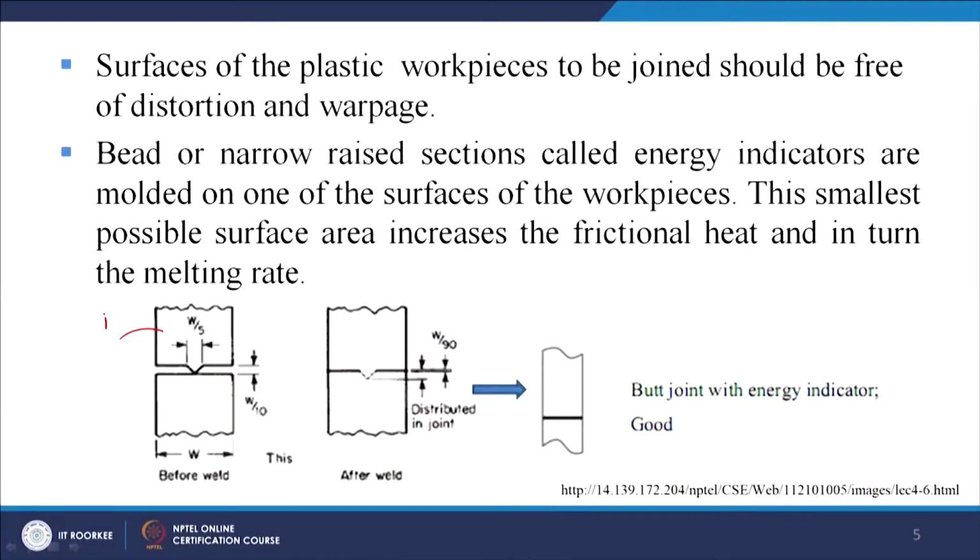One by one we will try to see, and with the help of the diagrams we will try to understand how we must design our joints so that they can be in mechanical motion under the frequency just mentioned, so that frictional heat can be used to produce a joint between the two mating parts. Now we can see on your screen, this is our first part, this is our second part, and we want to join them at this interface. The width is also given, W.